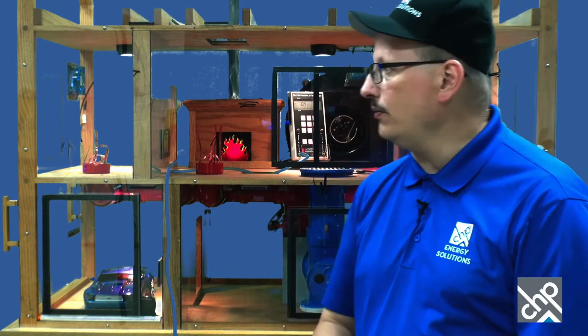You turn on the air handler fan, and then you hear a big slam, and the door is closed because there's a central return that's trying to get the air from behind that door, and then the door's almost closed. It just sucks it shut that final little distance there. Or you might see a carpet in a house, and then the carpet at the bedroom door has got a stain on the bottom of it, and that's where, if the door stays closed a long time, it's air trying to get out from under the door.